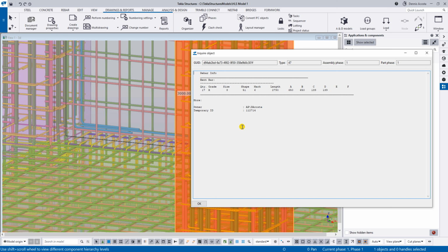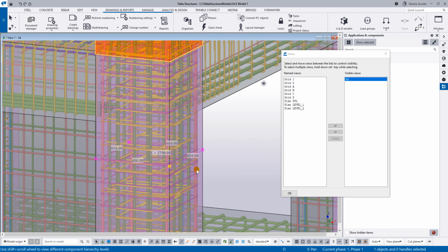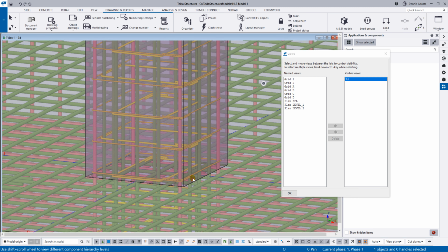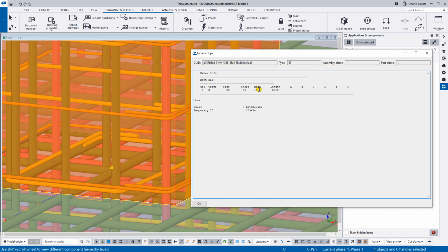But because I did not put the prefix, so it will be, but later on, if you want to put the prefix, then you can put R1, rebar 1, rebar 2, R1, R2, R3, R4, BR1, BR2, something like that. Okay? But at the moment, I don't put the prefix. Okay, next. Or maybe I'll get something else here. Let's say one of the column rebar, right click, and then here inquire. See, mark 10. Right?